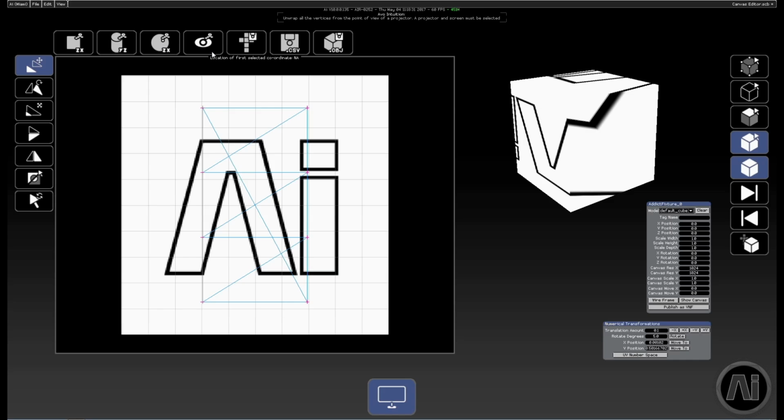So we also offer a point of view projection unwrapping. So this goes back to the very old days when we used to make content that was distorted within the content so that it would match its projection target in the final show. Now this was always pretty tricky because you had to know the exact positions of your projectors, your screens, the exact lens ratios, sizes, all that kind of stuff. But if you have worked in that way, you'll find it's very, very inflexible. Everything needs to be in the right place. So this one allows you to redefine a point of view from which you want the content to look good, and then to map it based on that.